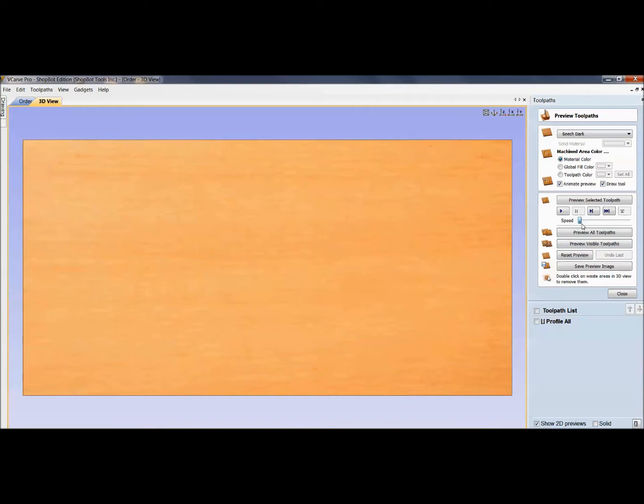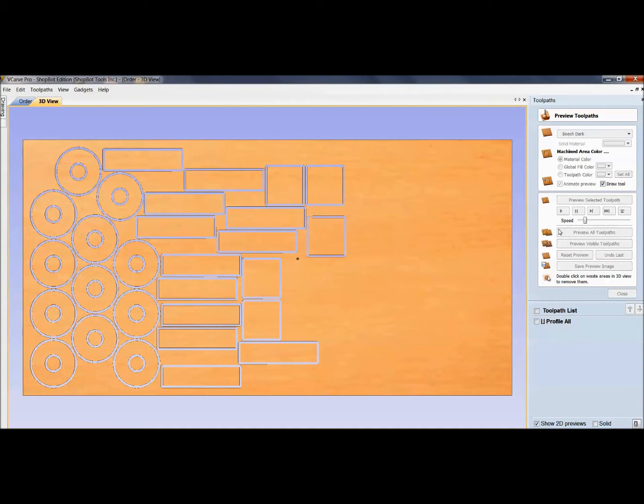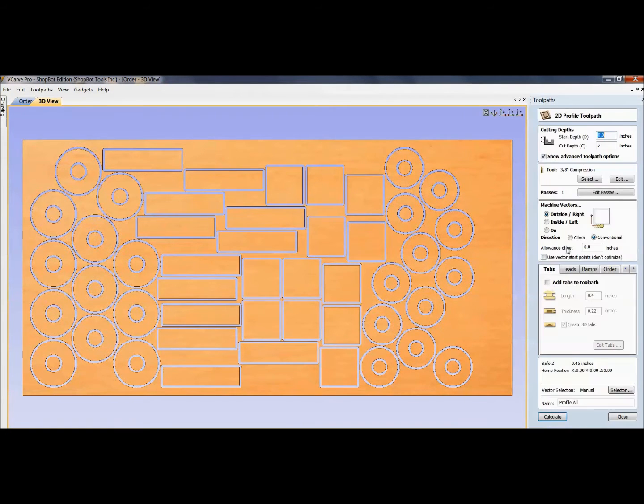So let me dial this down here in this preview, and we'll preview this toolpath, and as you see it's working from left to right. So on a typical 4x8 setup, as it got to the halfway point down in X, I could turn off zone 1 and 2 and put all the vacuum focused on the back half, zone 3 and 4. That would be a way you would want to select order.